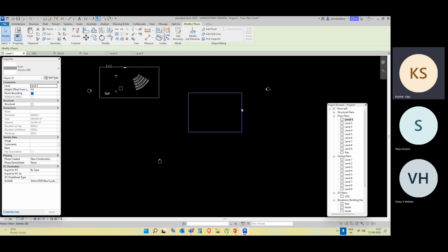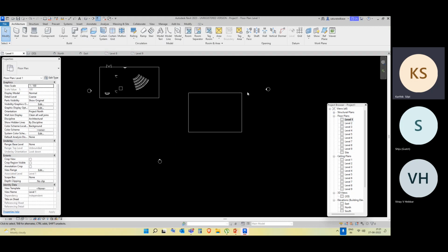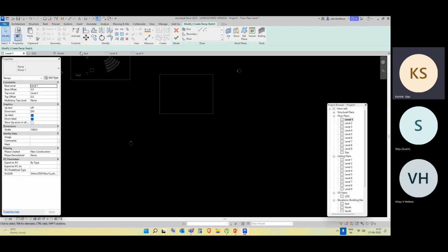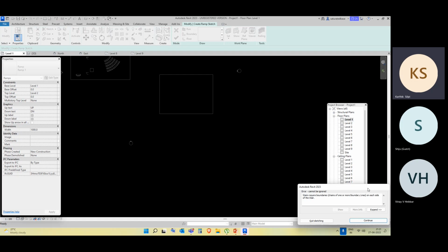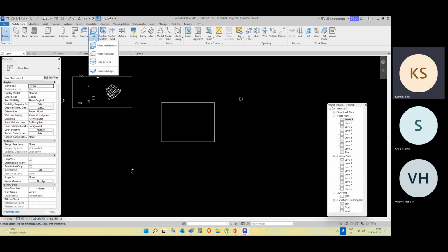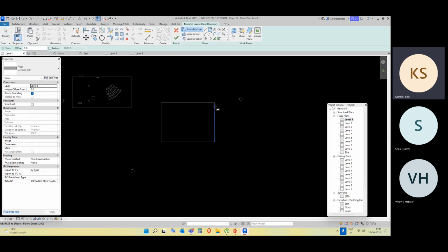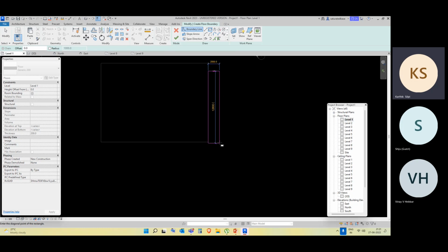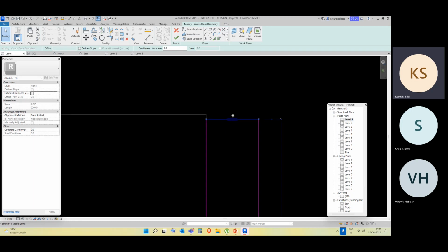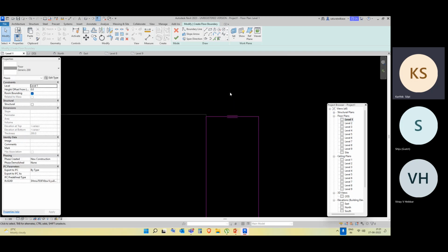So if my intention is to cover the first floor to the second floor, what I'll do is say this is my external most wall, and I'll just draw a ramp like this. I don't use ramp normally because ramp is not that good in Revit. It's only useful in specific cases, but instead of ramp you can just use floor itself and it is going to be way better than a ramp, like this. And it's going to extend till the end. You can just give like this. I'm just eyeballing like this.